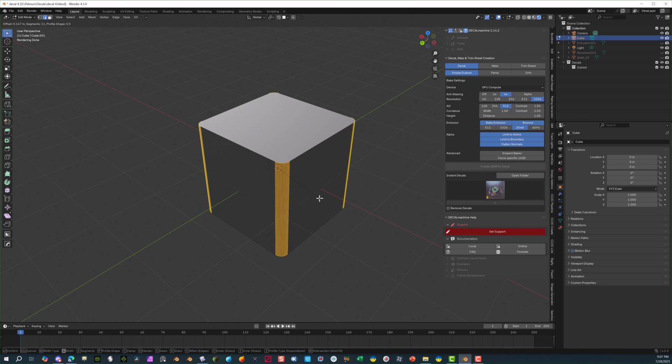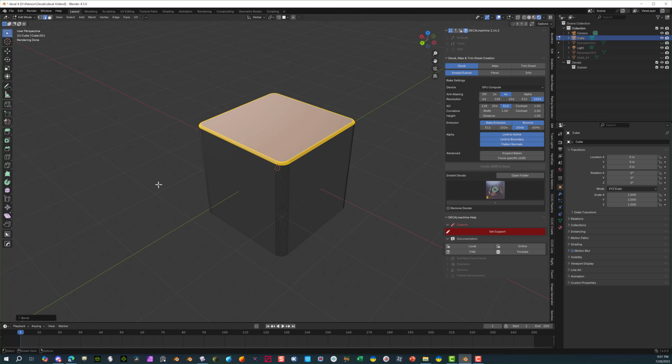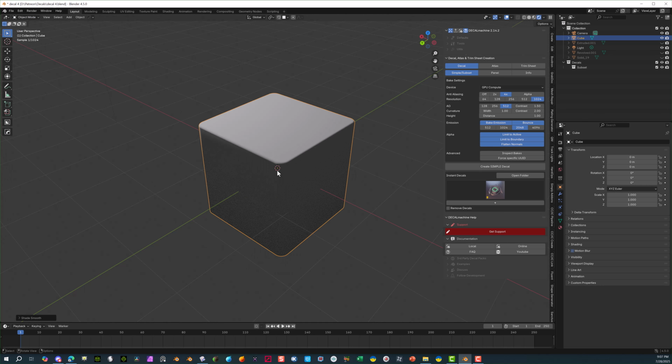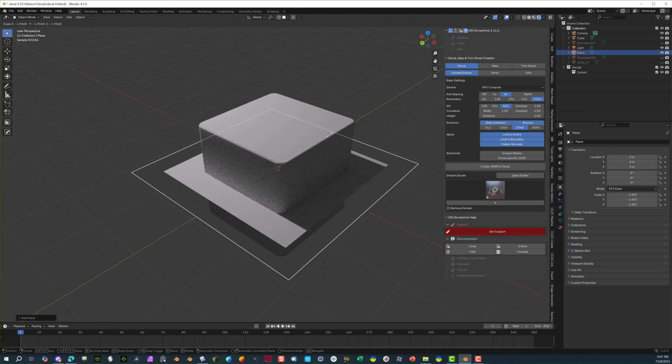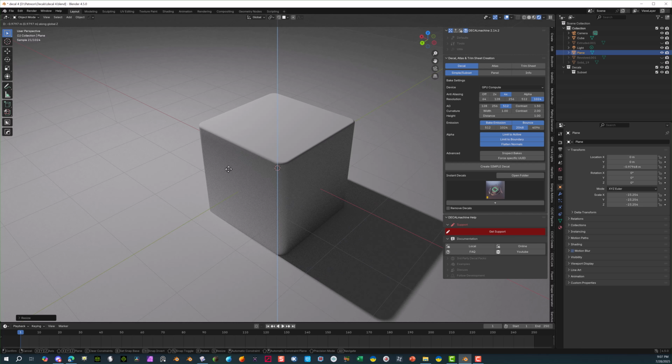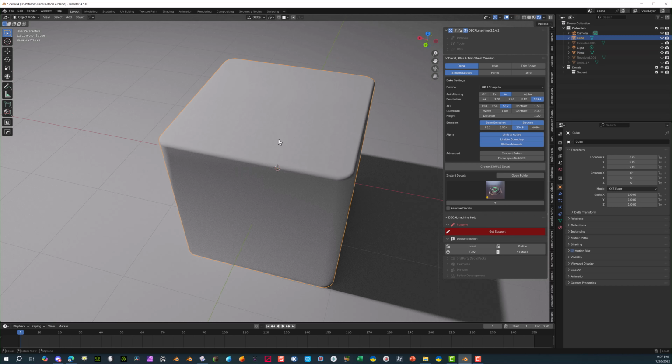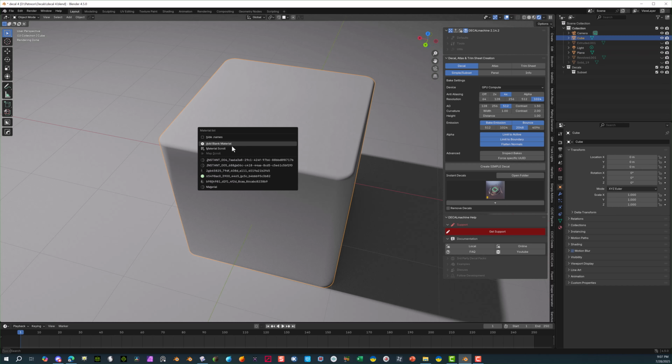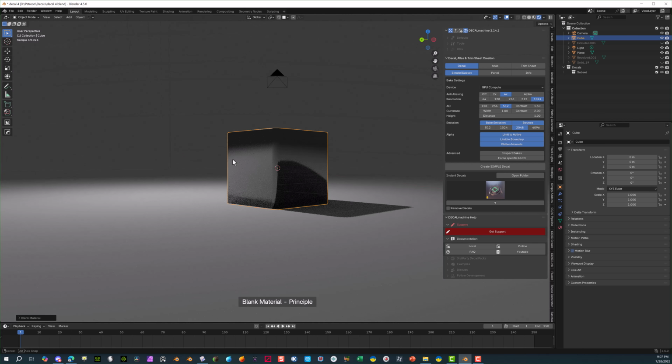I'm going to rotate it probably like 12 times, just like that. And then I'm going to select up here as well, and Control B. Again, we're going to pull this down just a little bit, make it smooth. And I'm good with this. Now I'm going to take this object here, right click, shade smooth. And I'm also going to add in a nice plane, just to make it look nicer. Scale, G key on the Z, down straight. Bring it right to the edge of this. And we could actually do an Alt M. This is Kit Ops, add blank material, fine.